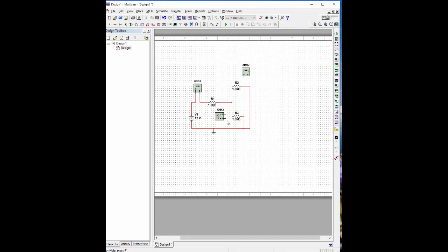So I want to measure this current that goes like that. So I will take these and then break this circuit like that. The same thing here, I want to measure this current. It doesn't matter whether we put the ammeter here or here. So put this guy here, and break the circuit so that the current can pass, become measured, and go back.